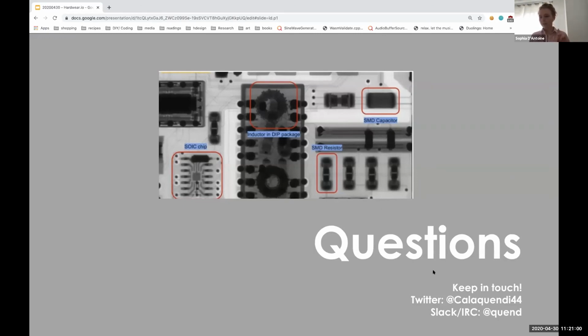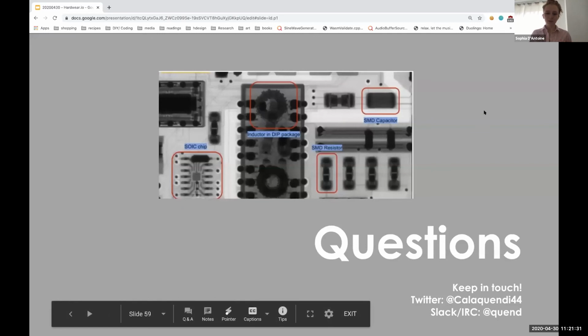I guess one more technique that I'll mention before I open to questions is one thing we like looking for is a component that we assume should be a passive component, is that actually an active component? Because as we see through a lot of backdoor proof of concepts and things like that, oftentimes you can package up an active component that looks and acts like a passive one with extra features. And so that's a good kind of binary check to do on parts. And then with that, I will open up to any questions on the floor.